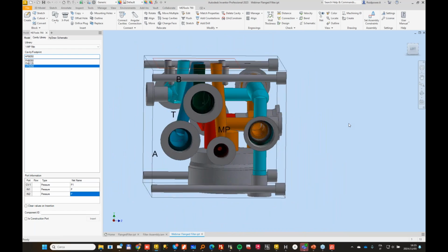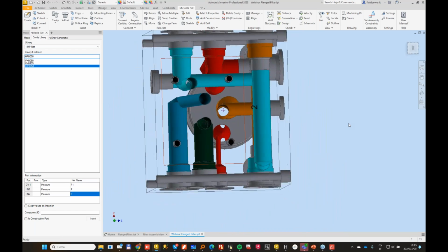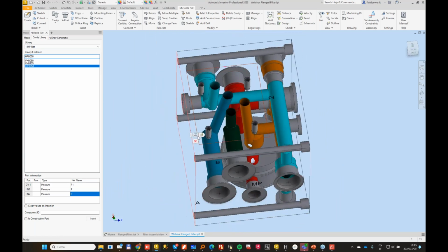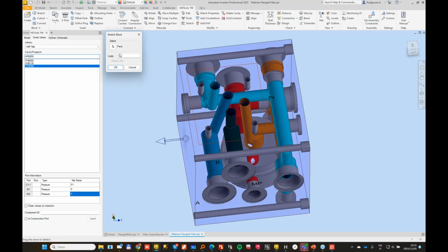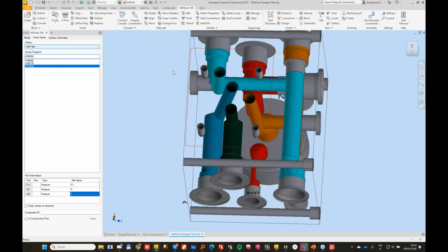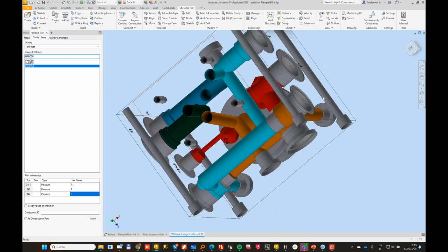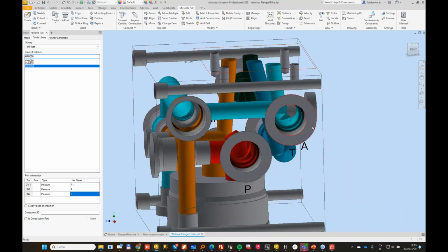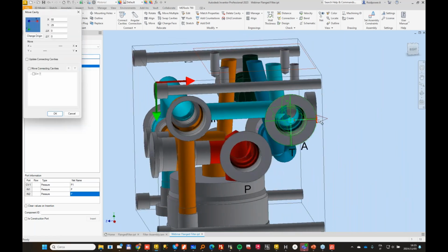By looking at it, we can see that we have some room for improvement. So we can remove some material from the back face, maybe 5 millimeters. So this ends up being a good decision, the idea to bring the filter inside the block. If we can save volume, then it's great in terms of manufacturability.